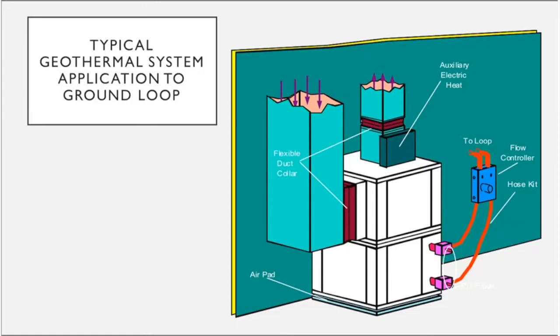Kyle, on that backup heating system, I'm just thinking there were 2 LEED gold multifamily projects built exactly the same, right next to each other at the same time. One with natural gas, the other with geo, and thankfully they were doing research on which one was more efficient, and we're finding that the geo was using way more energy, and then they kind of found out that the backup resistance heaters were just running all the time when there was no way to stop them. Is that a problem? This was a while ago, so if people do have it, is it easier to determine whether those things are running or not running?